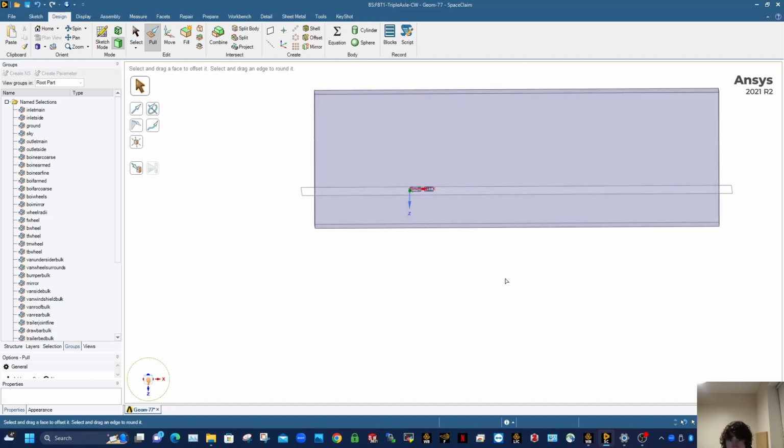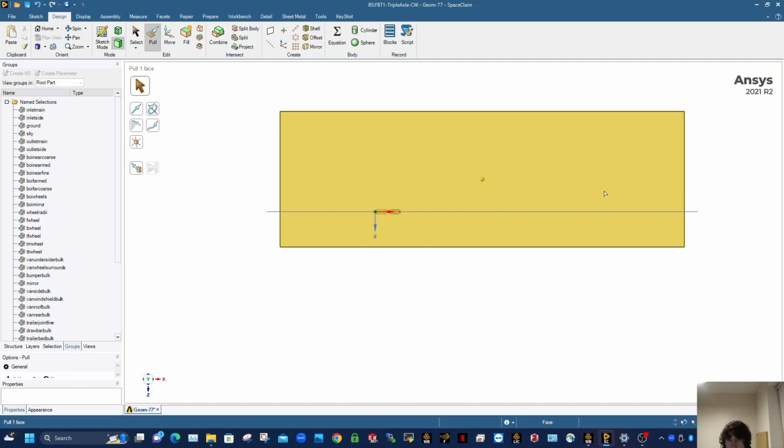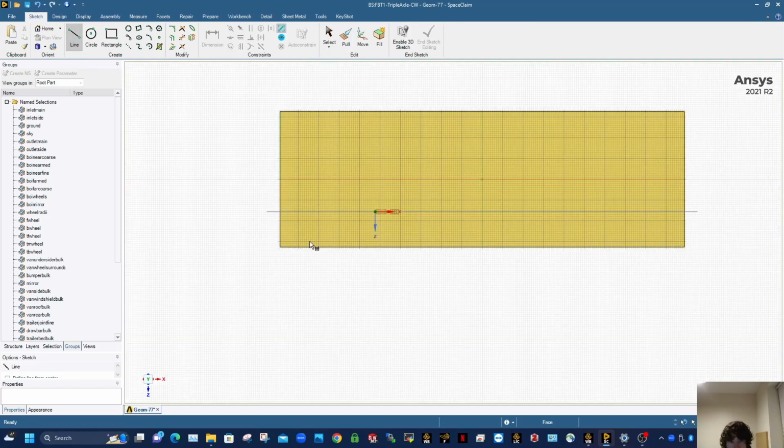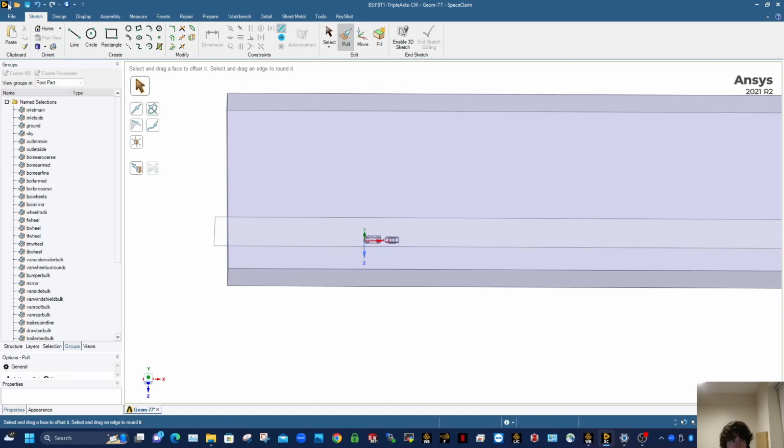And that looks reasonable now. You can see there's plenty of area here for the leeward side. What you could do as well is draw a line from there to there with an angle of 12.8 degrees, whatever angle your flow is at, to make sure you're happy with the shape of your domain. Grand. Click out of that. Okay, I'll just save this.